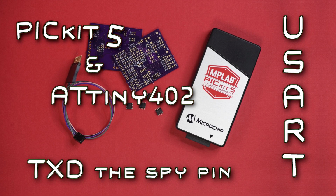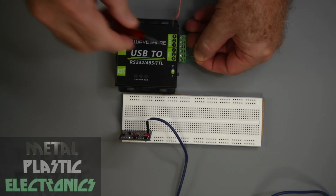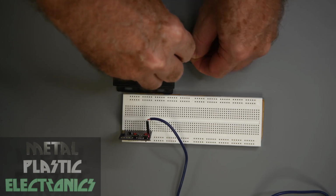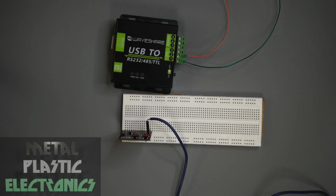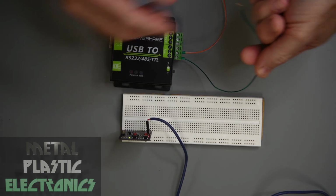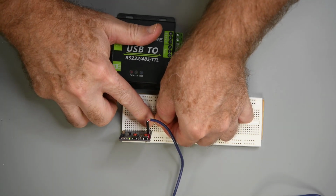A flashing or pulsating LED can only convey so much information. So the next step is getting a value out of the microcontroller. As long as the microcontroller has at a minimum a UART module and a pin I can at least share, I usually will send the data to a serial port on a computer. Sometimes I just need to monitor what is going on with a variable.